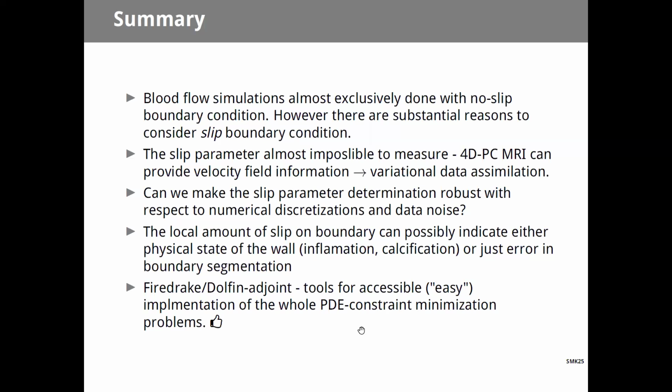You still can compensate by finer mesh. You go to the coarser elements. But for, let's say, the wall shear stress, so the forward problem, of course you get more accurate results, but on a given mesh, it's reasonable, good results even with the lower order elements.